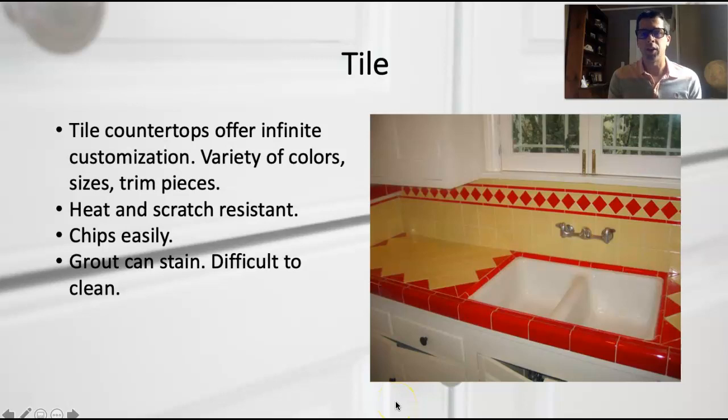Tile is a very traditional countertop material, and I just love these old post-war tile countertops. I just love this stuff. These are individual, I can't remember what these things are called, but bullnose tiles on the end here. And then this is called a pencil tile, this red rectangle. And then these are field tiles, these 4x4 tiles. And then these are field tiles just flipped into a diamond shape. And then these red ones are field tiles that have been cut in half and put in as a diamond.